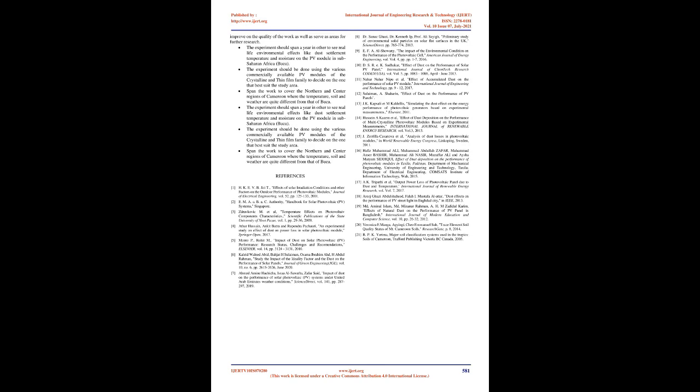Initially, one sheet was used in both clean and dusty conditions, and comparing the results gave a 20.2% and 19.7% reduction in power and efficiency of the module respectively. Cumulatively increasing the number of sheets, both clean and dusty, separately led to a progressive increase in percentage reduction of the module's power and efficiency respectively, up to 58% each for 5 accumulated sheets. These outcomes are depicted in figures 10 and 11 below. Fig 10. Percentage reduction of power of dusty module compared to the clean module.